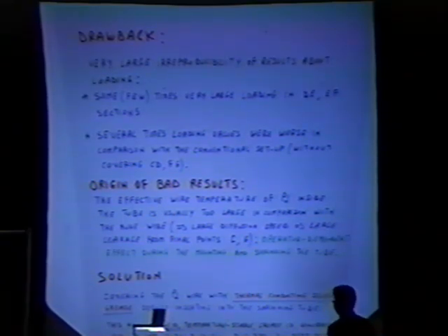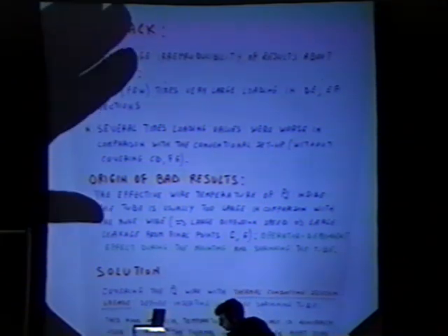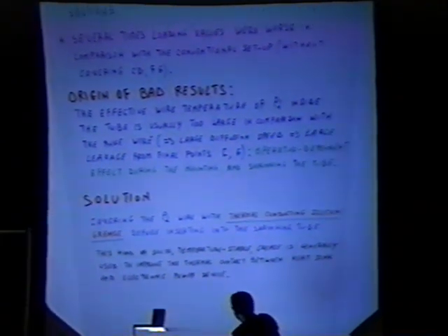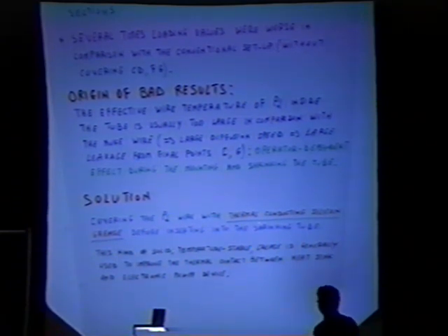We found a solution which is coming from the electronics world. We make some thermal conducting silicon grease around the wire, and over that we use a shrinking tube. In this way, we strongly reduce the temperature increase, and we make the system quite simple.